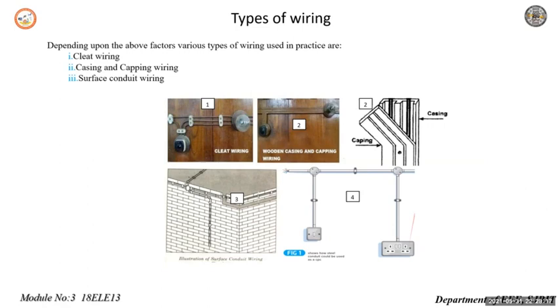Appearance: due to the wiring scheme, the beauty of the house and premises should not get spoiled. Cost: the funds made available by the consumer should be considered before recommending a particular type of wiring scheme. Maintenance: the maintenance of the wiring should be as minimum as possible. There should be scope for further extension of the wiring. Renewal of the wiring should be easily possible. The fuses and plugs should be easily accessible if at all maintenance is required.